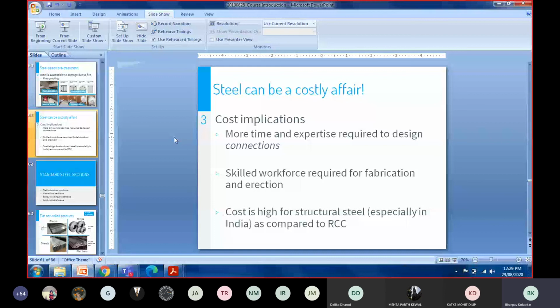Then it was too much for the client, and they asked us to review what are the other options that we could use. And then we worked with a composite option, wherein we would have composite beams and composite columns. And then we had only concrete option. So in the only concrete option, the sections were much bigger. And perhaps the architect wouldn't be very happy with these sizes of sections, because that might alter the kind of concept that he might be aiming at achieving.